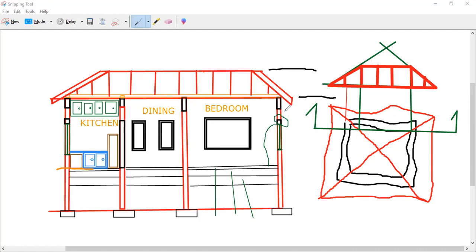Of course, you would offset that inside to get the stirrup and add those details to it if you're using the traditional method. If you are using AutoCAD Architecture, all of this would be really easy. I should be making a video on how to do your sectioning using AutoCAD Architecture. But for now, some schools are using the traditional method, so I still teach using both methods. I think that's enough for this drawing. So to get started, you would start here. You would establish your limits, and draw one line there. This line will be your finished floor.